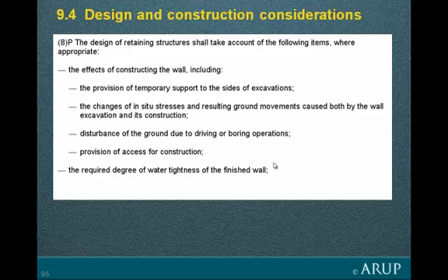And then, as part of these construction considerations, the designer needs to think through the provision of the temporary support, the changes to the in situ stresses that will have effects on surrounding constructions, the effect of constructing the wall itself, disturbance of the ground due to driving and boring, and so on. The degree of water tightness is not strictly part of a Eurocode requirement. Eurocodes are concerned with the strength of the structures rather than the water tightness.